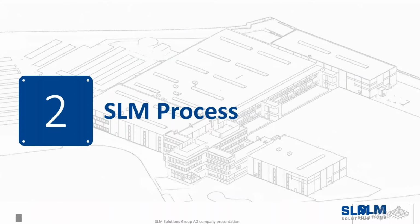So some of the direct advantages of the SLM technology are freedom of geometry and a much reduced build time in relation to casting. Part cost for small production runs is much lower in relation to casting. Getting castings can cost up to a couple hundred thousand dollars, especially on short turnaround, while in metal additive you can run them same day, same time.